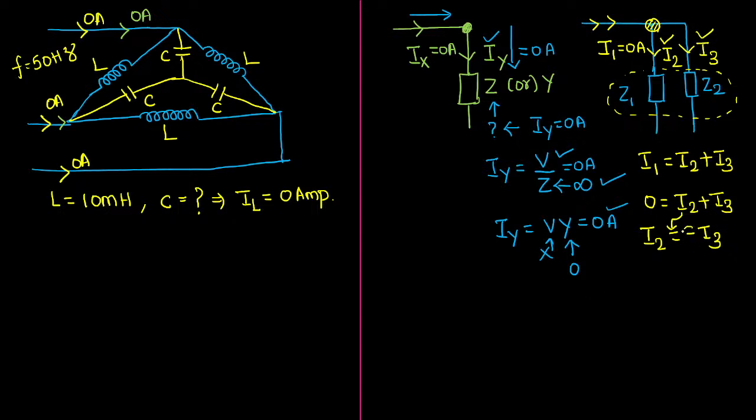See there, this minus indicates the value of I2 and I3 are equal to each other, but they are opposing. Magnitude of the two currents are equal, but sign is opposite to each other. That's why when we add, see, now there are two branches. One branch is consuming 10 ampere, another branch is consuming minus 10 ampere.